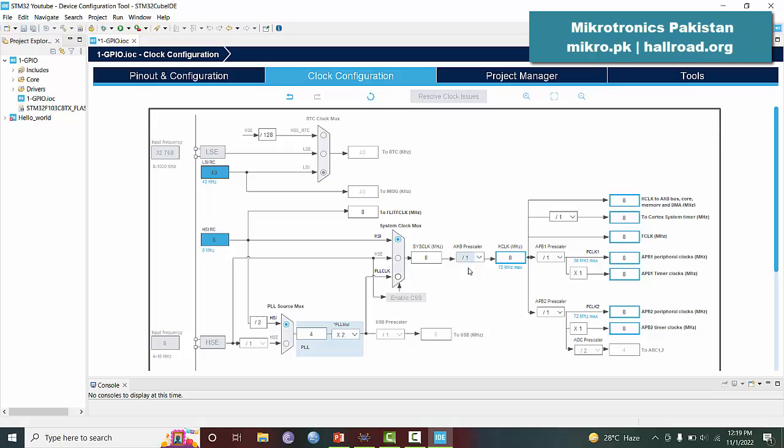Because these STM32 series microcontrollers are meant for power saving applications, they have a lot of options to save power. You can even change the power speed of individual buses, and as you know, these different buses actually power the different peripherals. So for this demonstration, we just keep all these things as standard.